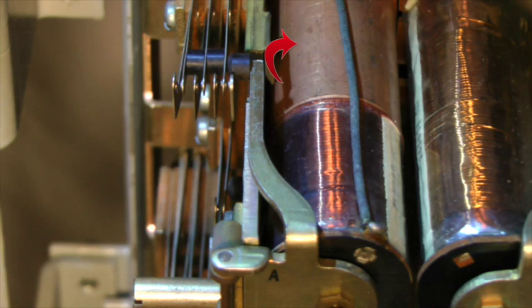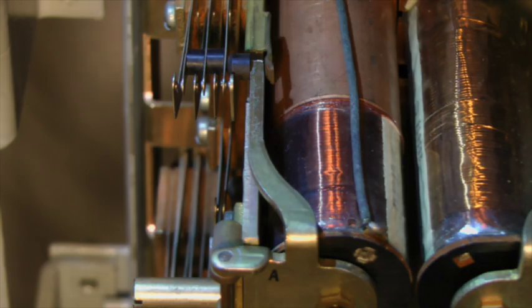When the A relay winding is de-energized, it causes the magnetic field around its coil to begin collapsing. This collapsing field induces a magnetic field around the copper slug, such that its polarity strengthens the field around the relay coil, slowing down the rate of its decreasing flux, thus delaying the relay's release.